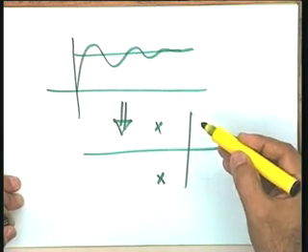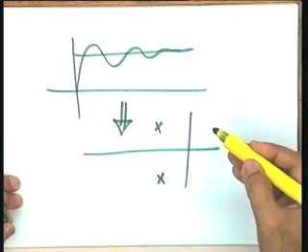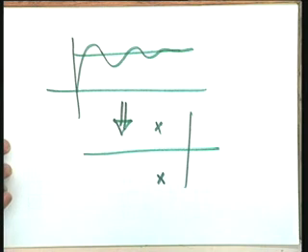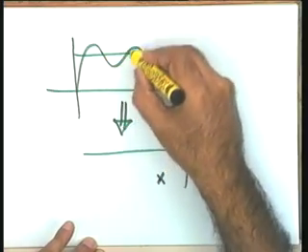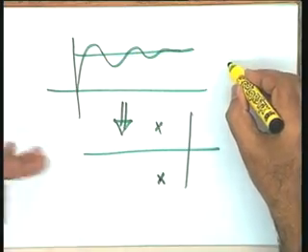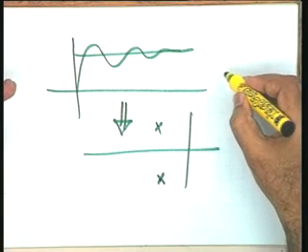Now let us assume that your open loop transfer function does not have these pole locations. So in this particular case, I want to claim that by a suitable design of D1 and D2, that is by suitable design of the controller D(s), you will be able to force the pole locations of the closed loop system onto these points, so that the dynamic response of the closed loop system follows the prescribed dynamic shape.